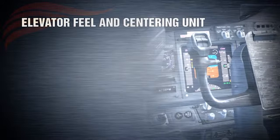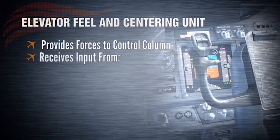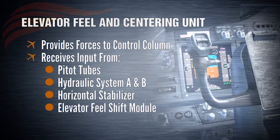The elevator feel and centering unit is a computer that gives variable control column forces as the airspeed changes and the horizontal stabilizer moves. The elevator feel computer receives input from pitot tubes through pitot ports, hydraulic system A and B, horizontal stabilizer, elevator feel shift module, or EFSM. This last mechanism operates during a stall, providing 850 psi of hydraulic system A pressure to the elevator feel system.